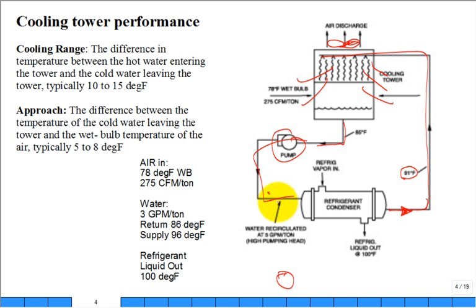And then you take and throw that cooler, lower temperature water through a heat exchanger, which is picking up heat from refrigerant that is condensing. So this is the condenser side of the chiller. The refrigerant's condensing, and then that's warming up the water. So the refrigerant comes in maybe saturated vapor and goes out saturated liquid, negligible pressure change, but maybe it's 100 degrees F, 110 degrees F, something like that.